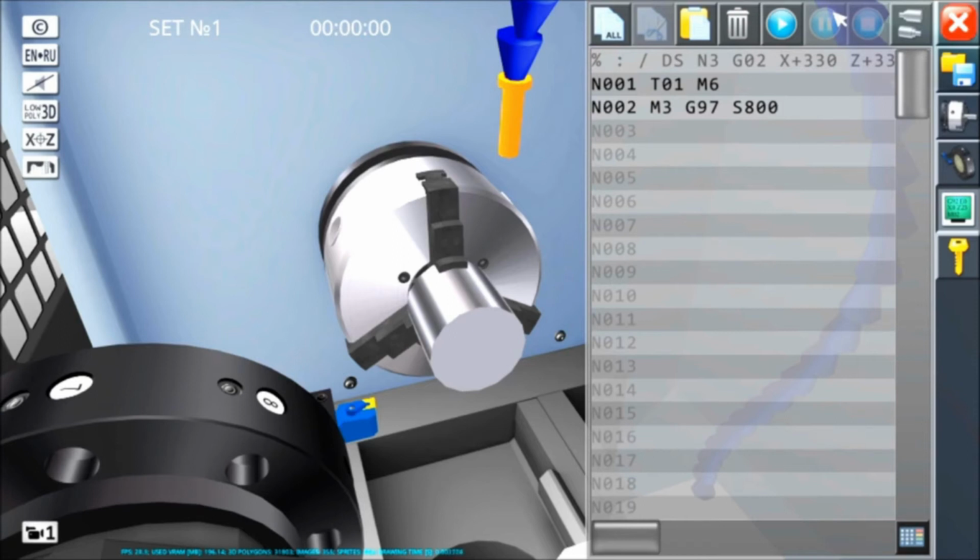G95 always better to put it. Normally the machine starts already in G95, but it's not guaranteed, so let's put it because we don't know who has worked before us on the same machine. If he used G94 then we are in millimeter per minute, that is, even with the chuck stopped in working conditions we can advance the tool. G95 instead works millimeter per revolution, so we can only work when the chuck rotates.